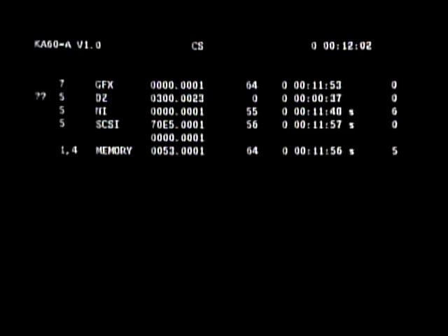Each line of this report consists of a single or double question mark if there are errors, the MID number of the module being tested, the device mnemonics, a status and error field. Refer to the VAXstation 3520-3540 maintenance guide to decode these fields.